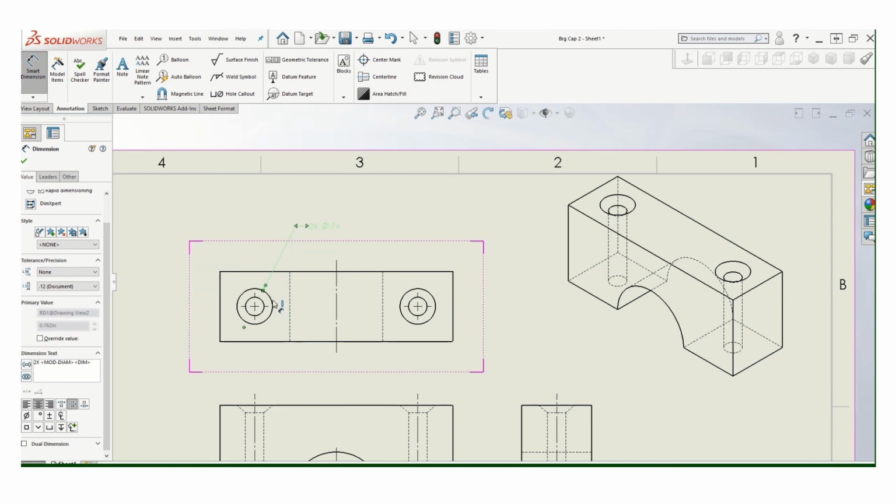Now that's that big hole. That's not the right diameter, so I'm going to cover that up. I'm going to put the diameter symbol. Oh, I got a diameter symbol. 0.40. Go to the next line, and I'm going to do countersink, diameter 0.76, space X, and then 82 degrees.